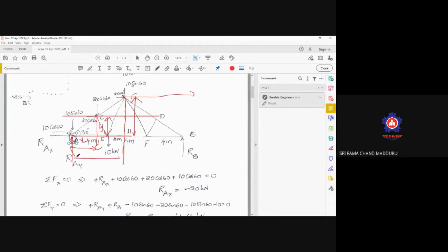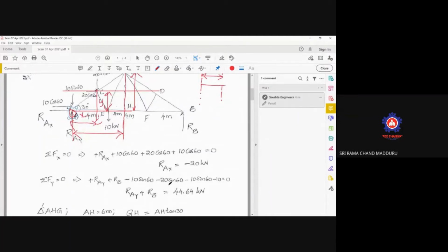In general, the principle to calculate the moment is this: whenever a force is acting, and you want to take moment about a point, draw a line parallel to the line of action of the force, and the distance between them, the perpendicular distance, is to be calculated. Otherwise, there is another simple way to calculate the moment also. I will show that one.